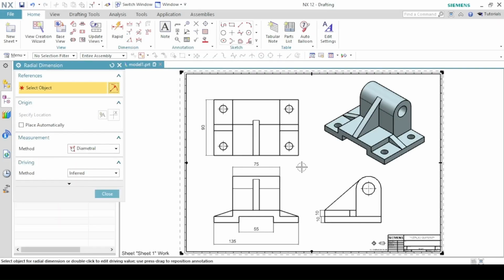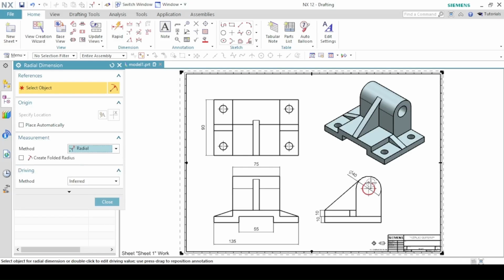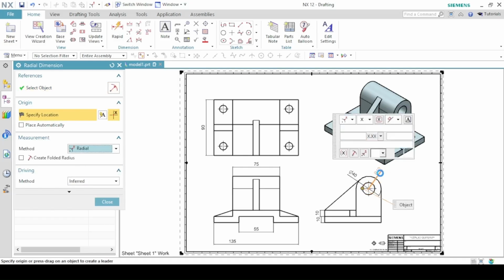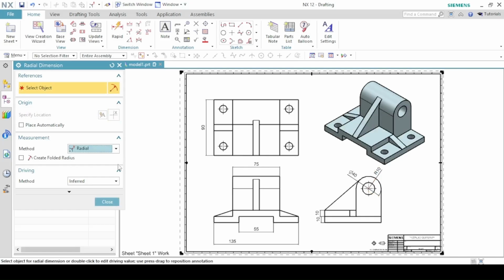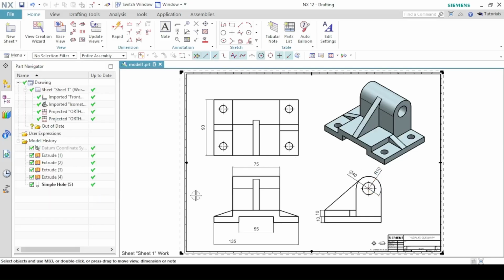And for good practice, the dimension of the outer circle should always be diameters. So the diameter is 40. And then for inner circles, we mostly use radius. The radius is 10, meaning the diameter of 20. Click close. Now, since the outer diameter is 40, that means the horizontal dimension or the horizontal distance here is